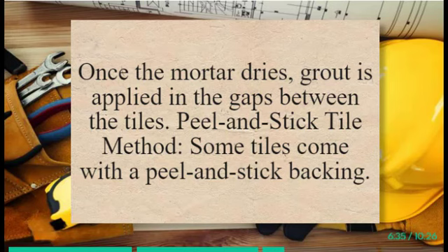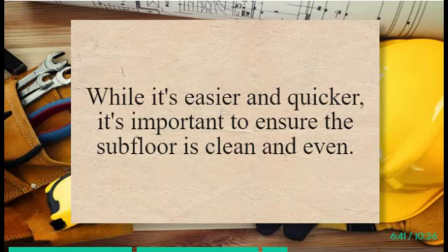Peel and stick tile method. Some tiles come with a peel and stick backing. This method involves simply removing the backing and sticking the tiles directly onto the prepared subfloor. While it's easier and quicker, it's important to ensure the subfloor is clean and even.